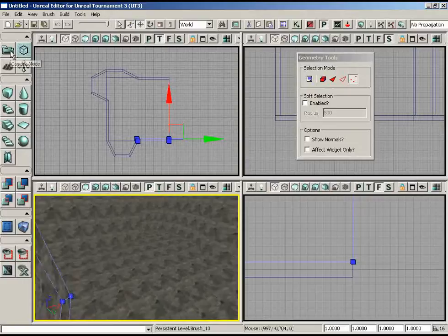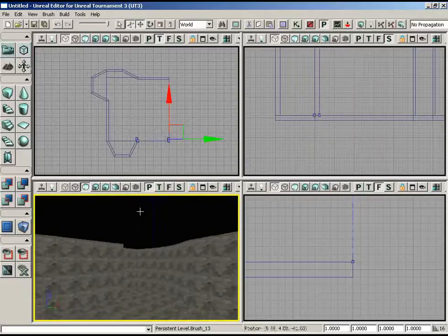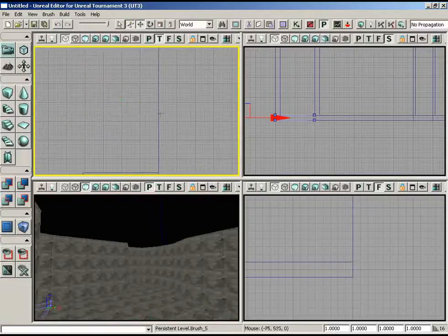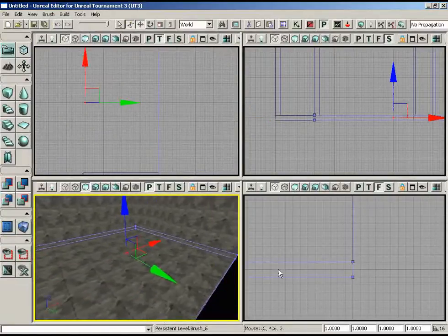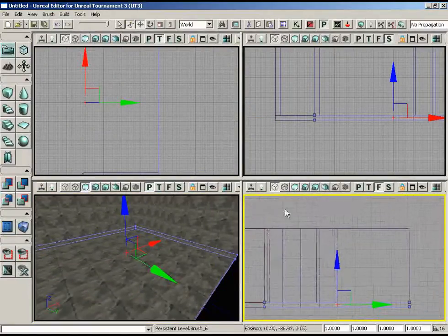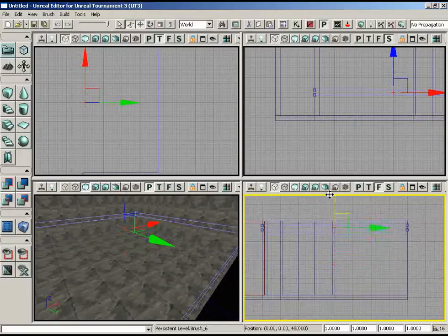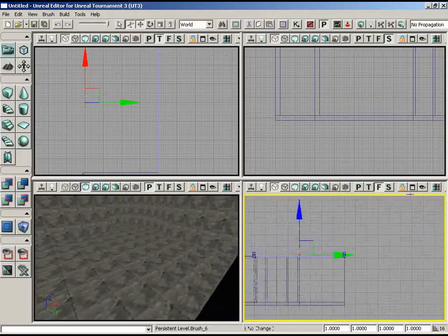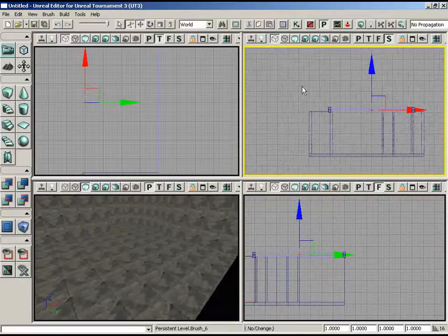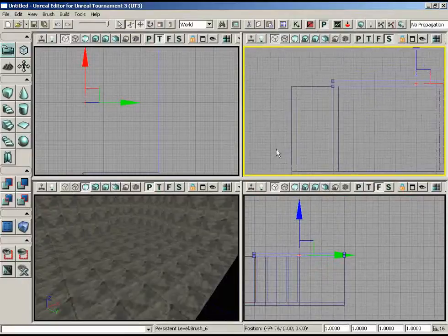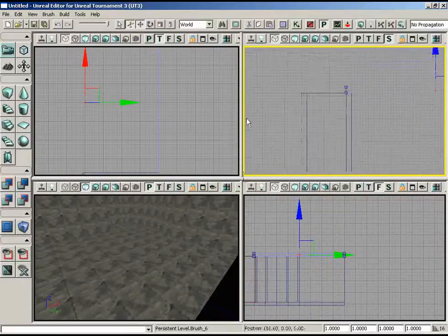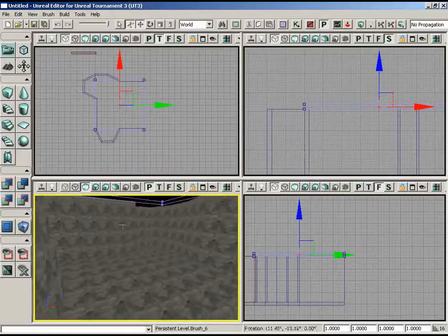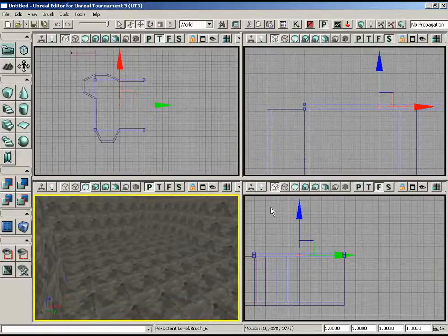Now let me jump out of geometry editing mode for a minute, and let's grab the floor brush. And that's the wrong part of the floor. Let's grab this one, the full floor, and let me duplicate that up to the top. So once again, Alt-drag, and I'll set that up to be just above all of the wall brushes. And looking at this, we should have a height of that lined up. And really I should have grabbed all the floors. I'll leave that in place.